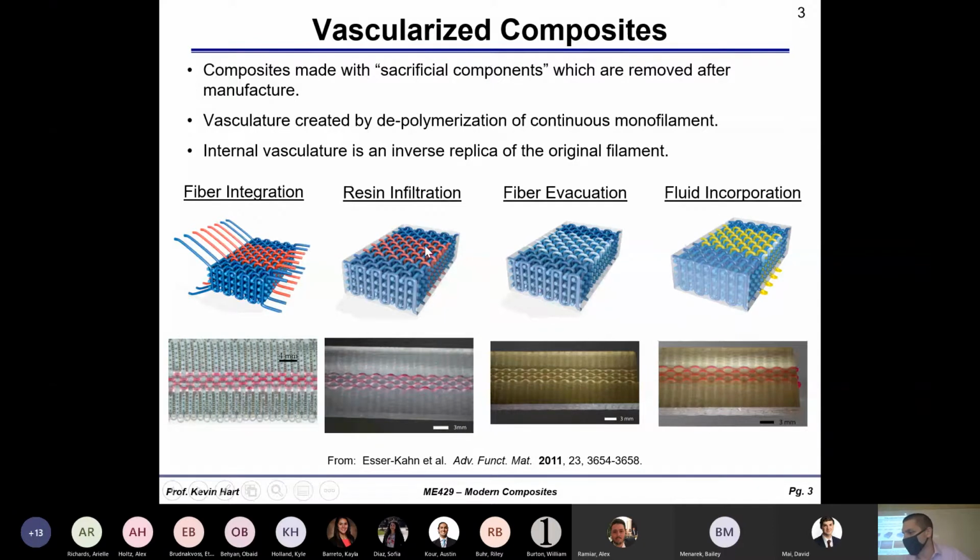And so you have these fibers that are in the structure itself that remain after the solidification of the matrix material. Then you raise this to high temperature. We use about 200 degrees Celsius and put it under vacuum pressure, right? So you're pulling vacuum on this thing. And the fiber that's inside here actually sublimates, goes directly from a solid to a gas. And you sublimate it out and you trap the fibrous materials that are coming out.